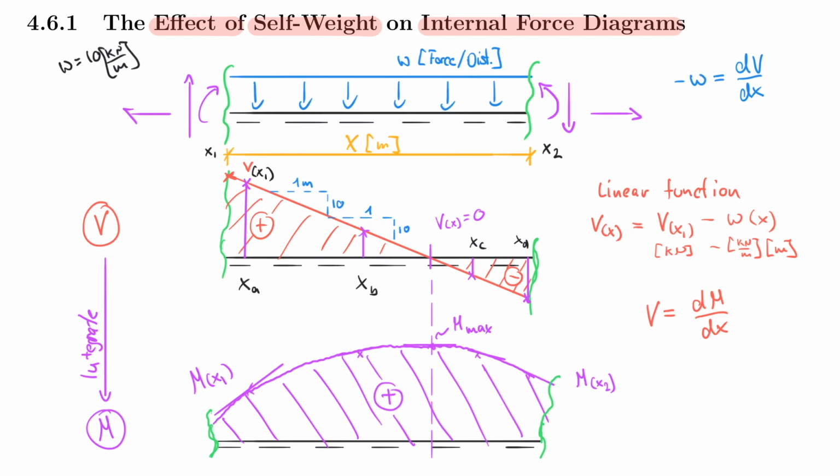And so we related each of these shear force values to the slope of the moment function, because we know this here. And therefore, we can unmistakably draw the parabolic function and the shape of this moment diagram. And let's talk about the unmistakably part here for a second. So students sometimes tend to think, this is positive here, therefore my moment diagram must be positive. But you can already tell from this diagram that this is not the right logic, because here it's negative and my moment diagram is not negative here.